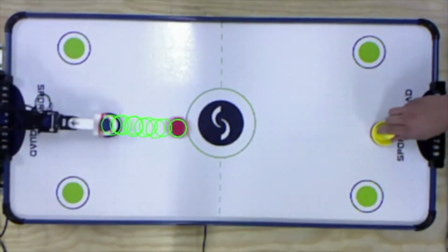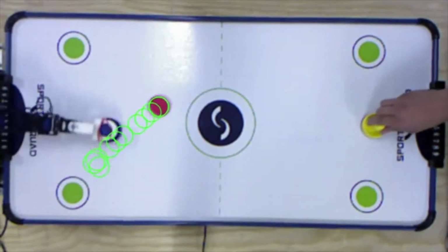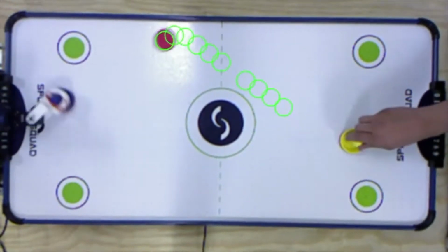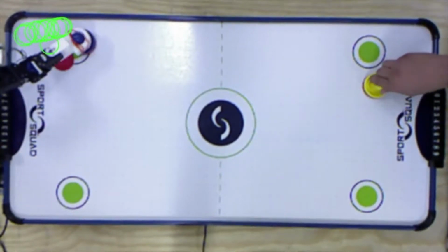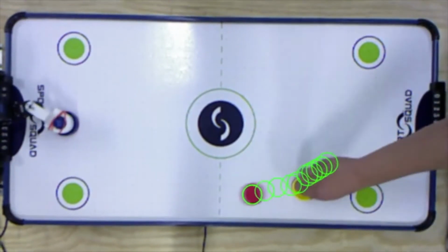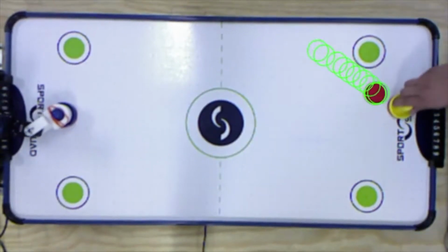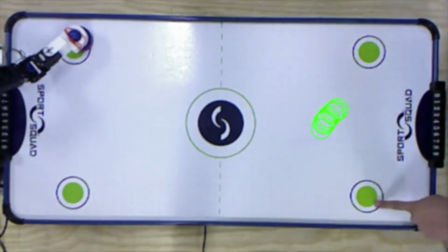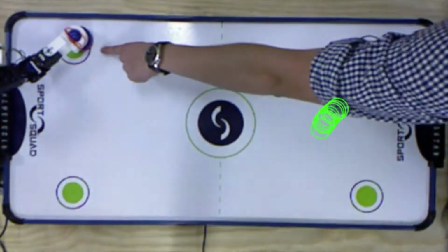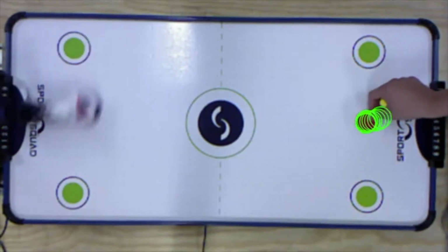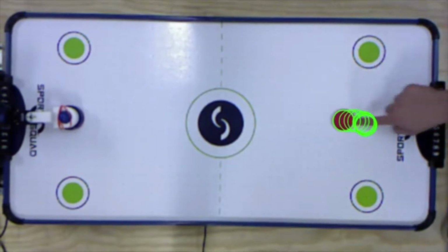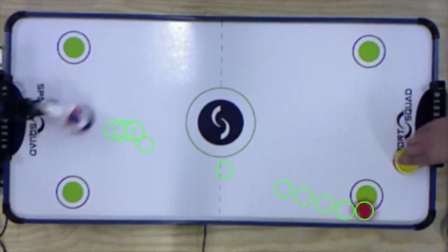The next challenge was that the coordinates of the puck given by OpenCV are with respect to the Kinect's reference frame. We wanted the coordinates of the puck in the robotic arm's reference frame. To complete this task, we used the green calibration markers you see near the corners of the arena. We measured their position with respect to both frames and solved for a transformation matrix that would translate from the camera's frame to the robotic arm's frame.